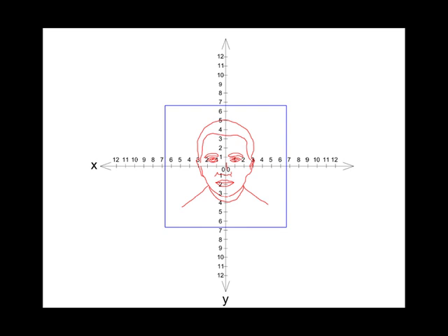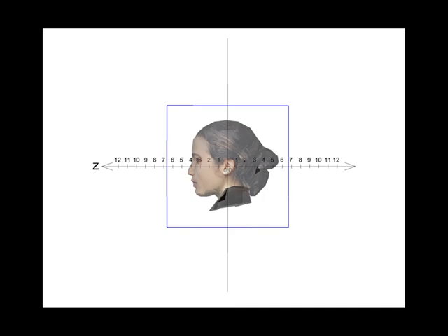If we turn the view sideways, we have another plane now, and we have what's called a Z-axis, the third dimension for depth. In other words, we're looking at the side of this face now, and if we again trace those lines and extend those lines to the plane of projection, that flat sheet, we end up with a profile of this face.